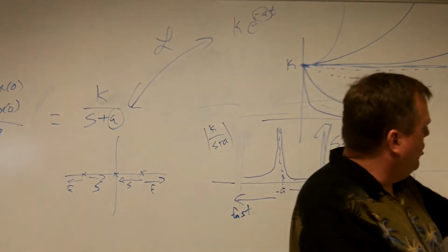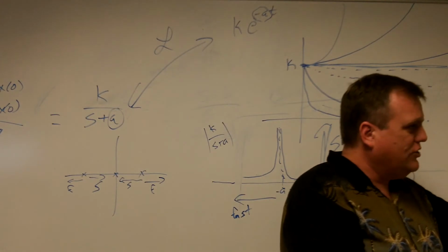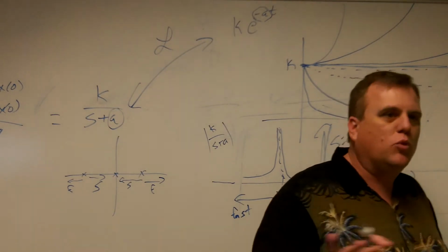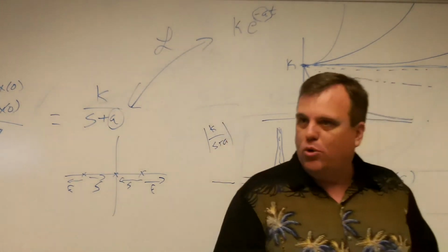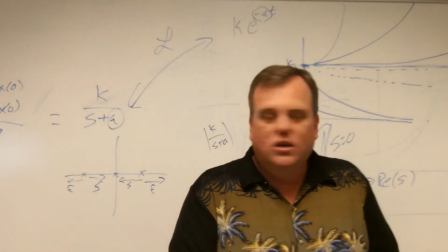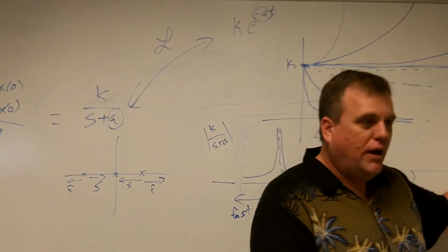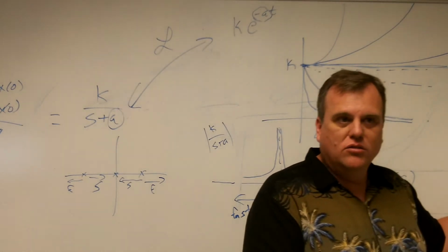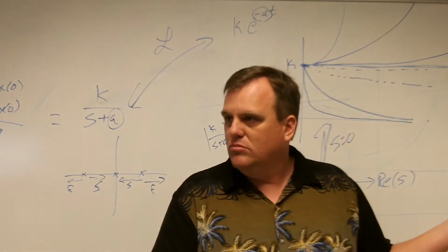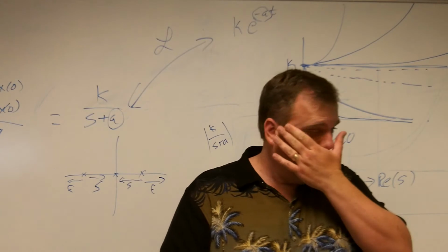So if I see them all and there's a boundary zone before that axis, I know that no matter which one you excite, no matter which one of those poles is dominating the response, it will finish by a certain time covered by that line. It's a minimum requirement. Does it make sense?